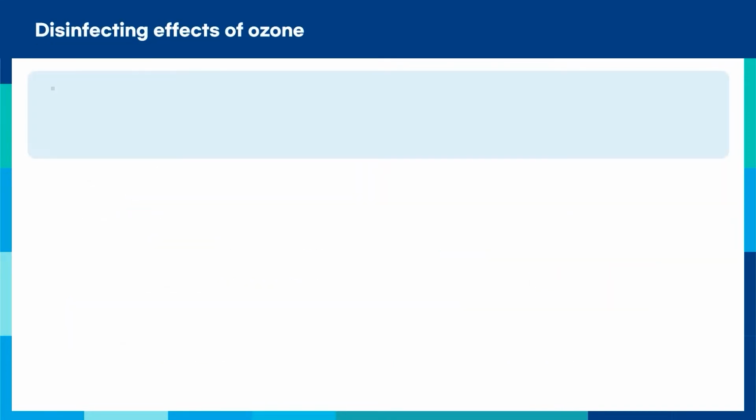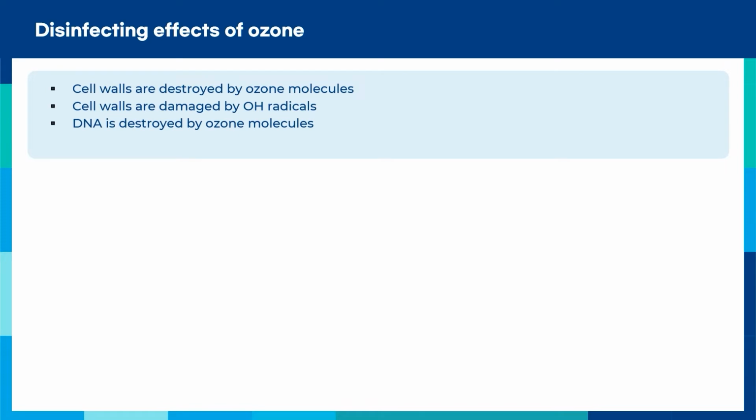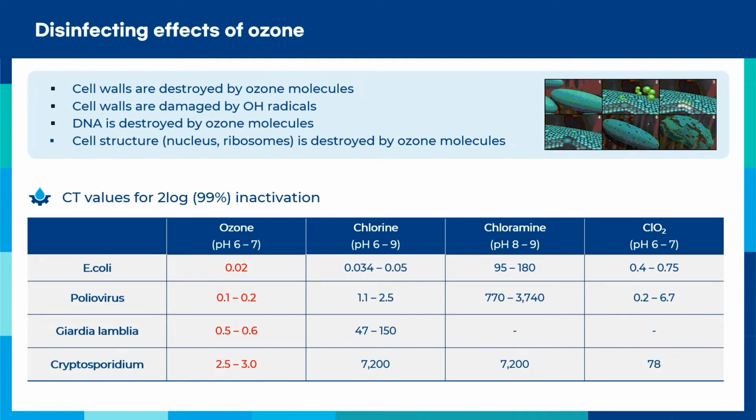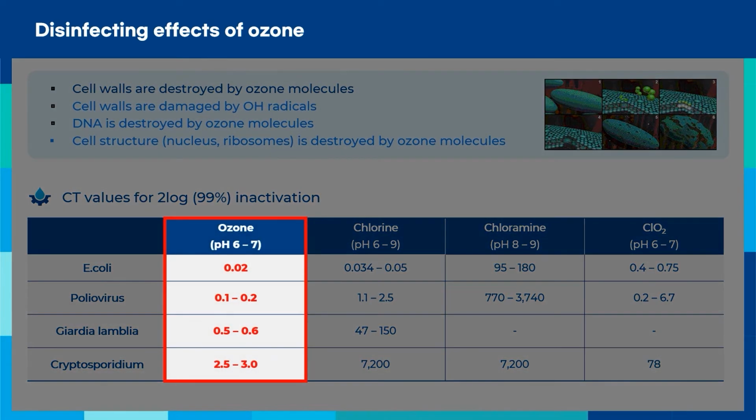Ozone has been proven to be the most effective disinfectant in almost all investigations and studies. The sterilization principle of chlorine damages the enzyme by permeation of the cell wall. But ozone shows a strong sterilization effect by cell lysis of the bacterial cell membrane. Ozone has 5 to 25 times higher disinfection effect against viruses and bacteria than chlorine.